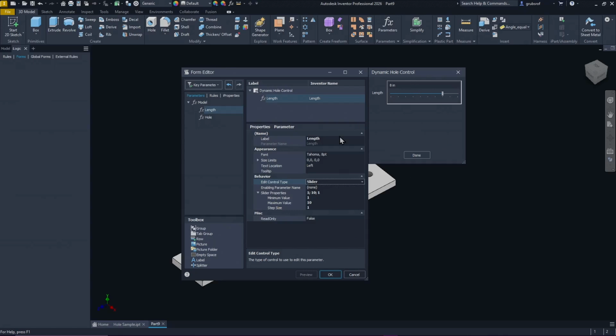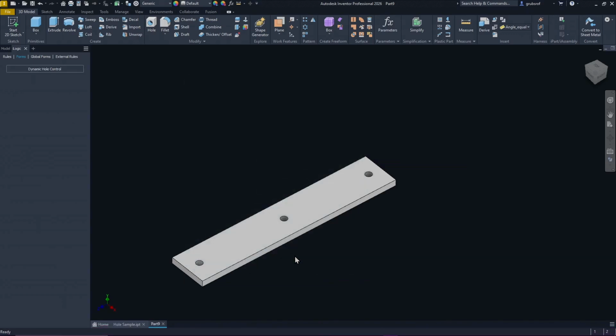So right now, we did 8, but this parameter down here for max says 10, so that's why you see this extra here. If I accepted it right now as it was, it would be 10. So I'm actually going to make this 15. The minimum distance on that, we're going to leave it at 1, and then we're going to do increments. Now you see the tick marks? If you do like 0.25, they'll get smaller. So that's the increments of the slider. Let's say OK to that.